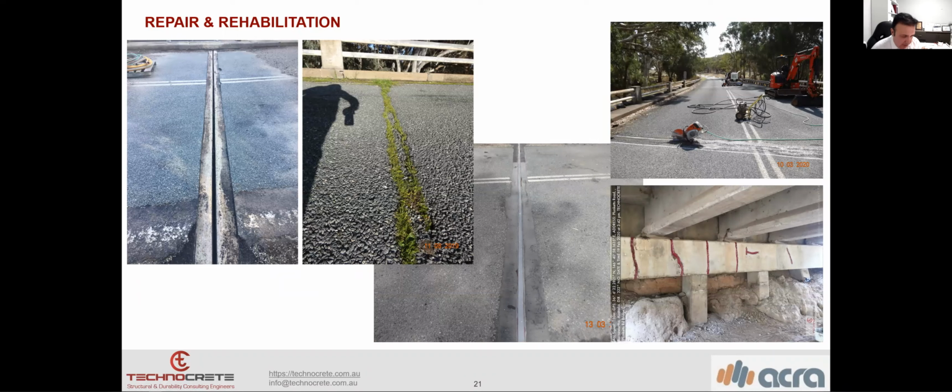The most important problem with that bridge started with the leaking water through the deck joints, from the expansion joints. Because they used high silicate aggregate, moisture can accelerate the ASR reactions.